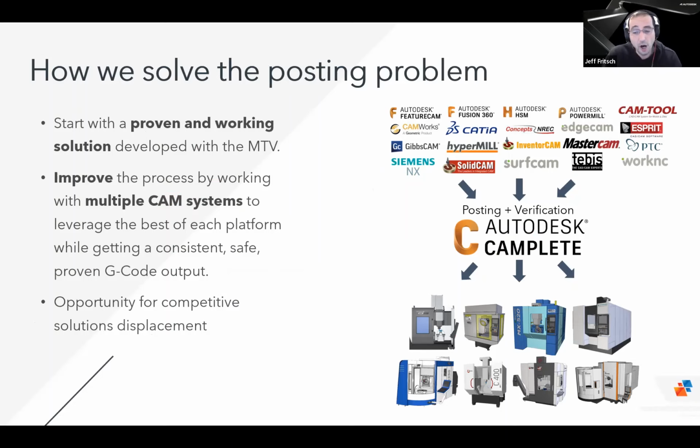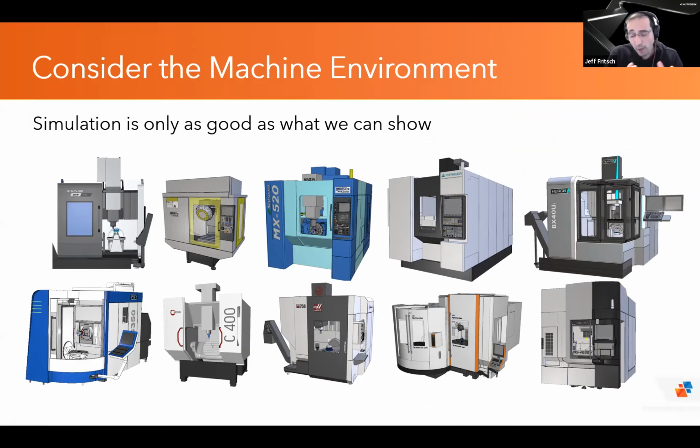It could even be a combination of all of those inputs, with a centralized common post-processing engine where we'll also have the G-code simulation built within the post-processor. So it's both elements, the post-processing and the G-code simulation, built one within the other, so that we can not only provide proper code generation for that equipment, but also a very detailed simulation to have a very clear understanding of what is going to happen.